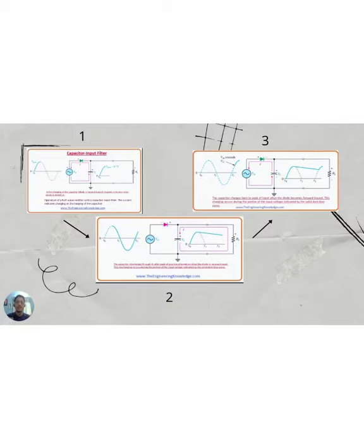In figure 2, when the input signal moves down from the peak point, the diode becomes reverse biased and the capacitor is still charged. Throughout the residual portion of the wave, the capacitor can release charge only through the load resistor RL at the rate defined by RLC, where the time constant is longer than the time interval of the input signal.